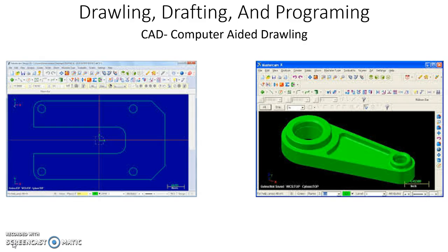We also use a program to draw, a computer-aided drafting program. We use specifically Mastercam in our class. There are several others. Mastercam you can use to make prints for manual machining, and these prints would have the way the part looks, 1 to 3 views so that you can see how it looks. It would have the dimensions, length, width, height, spacing for holes, spacing for little cutouts, all the information you need to know where to make a cut.